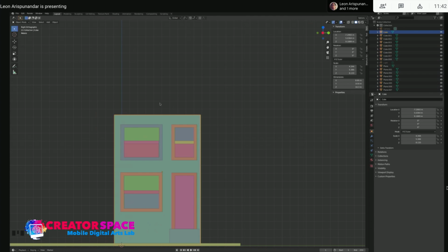Before you put any modifications or start texturing, what you want to do is clear all transforms. So you want to set everything back to original, which is 0, and the scale to 1. In order to do that, we want to apply, Control A, all transforms. See, everything's reset into 0 and 1. If you don't clear your transform, whenever you add modifications or textures, it becomes really wonky, I guess, right? Because you stretched it, you made it wider and everything.